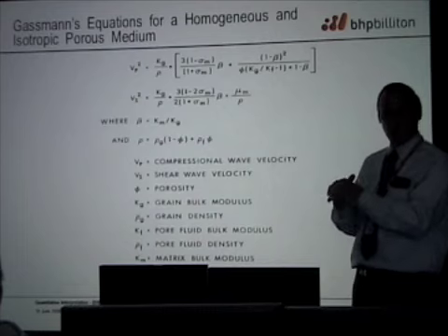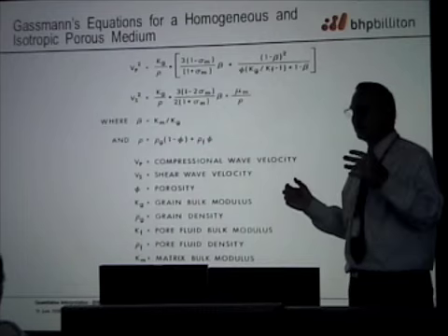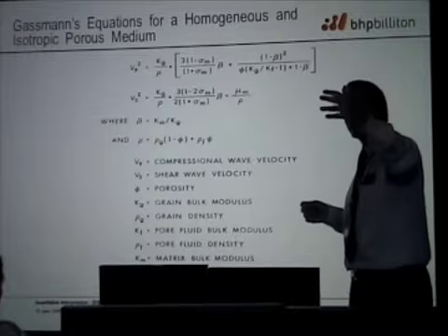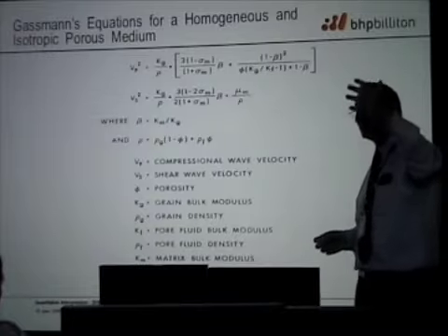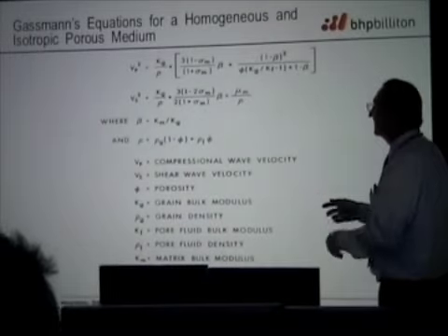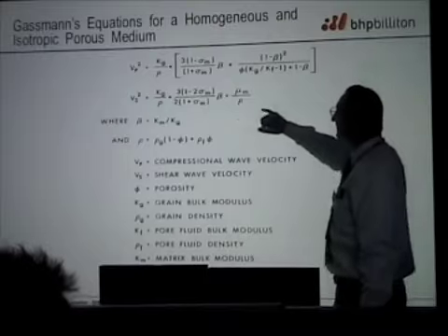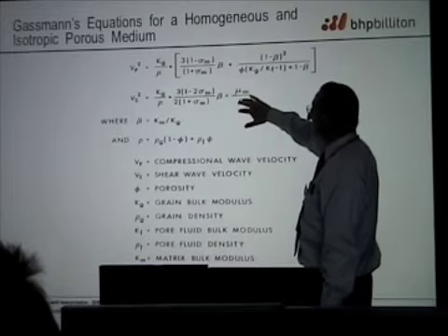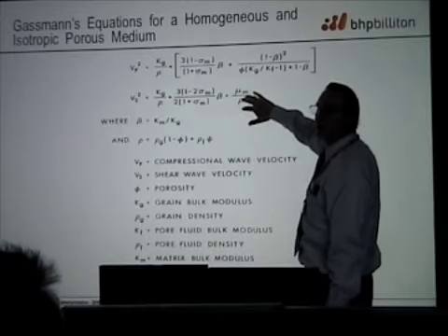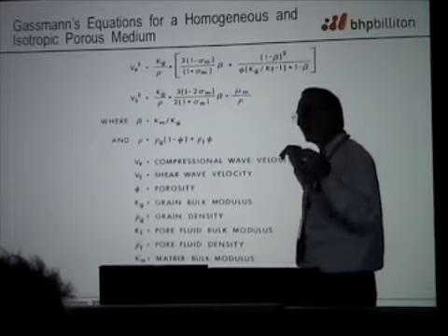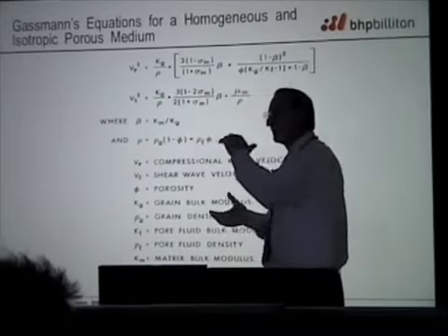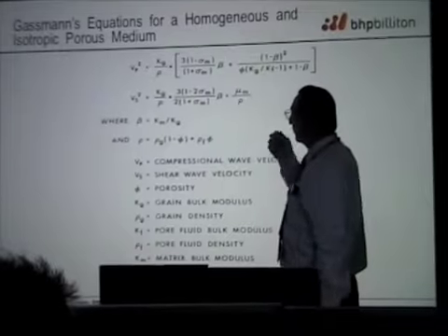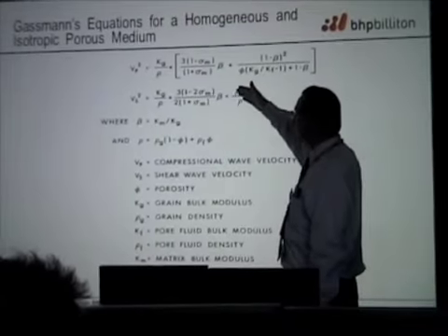The density and the bulk moduli of fluids are related: the higher the density, the stiffer the spring, so the higher the bulk modulus. So gas or oil will be less dense and also have a lower K than brine. That's what we're going to do: substitute in a hydrocarbon, which is lighter and more compressible than brine.